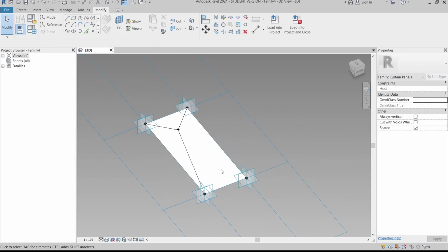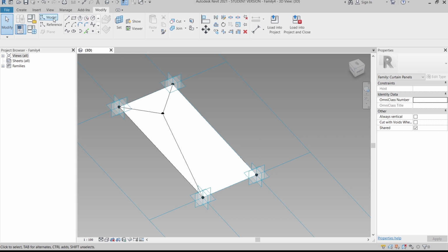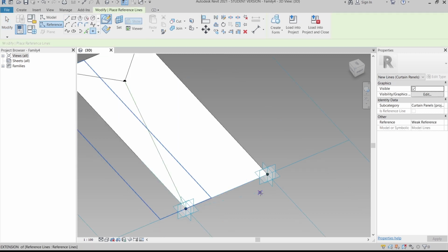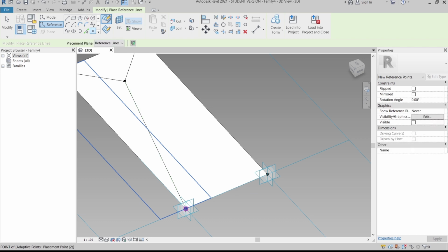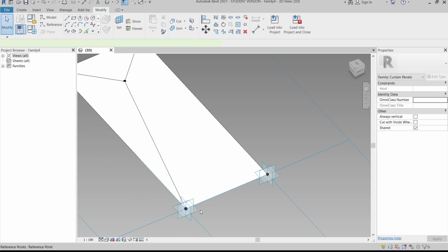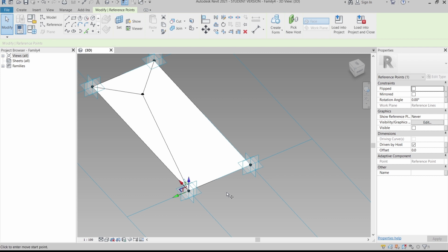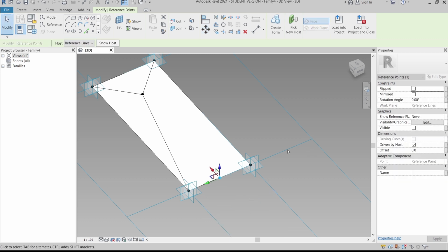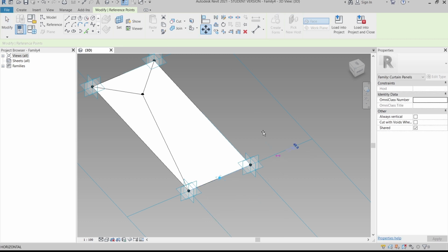Let's create another offset point there. To create that, I need to go to reference. The same method as before, just go to point. Then select this guy over there here. Then I can select the point here. Then of course I need to move it there, 500 by 500. Make sure our line is straight, 500 millimeter. Then I can move from here another 500 millimeter as well. Let me see, first 500 millimeter.